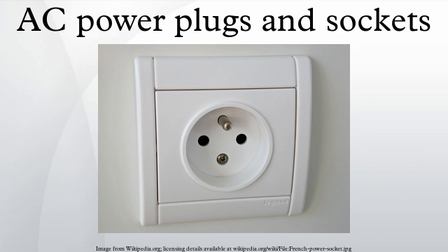JIS C 8303, Class II unearthed. The Japanese plug and socket appear physically identical to NEMA 1-15. The Japanese system incorporates stricter dimensional requirements for the plug housing, different marking requirements, and mandatory testing and approval by METI or JIS. Older Japanese sockets and multi-plug adapters are unpolarized. The slots in the sockets are the same size and will accept only unpolarized plugs.